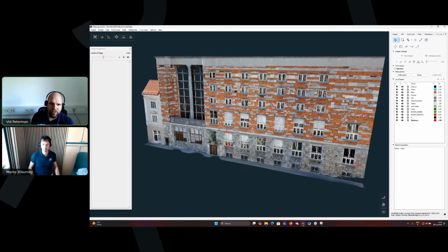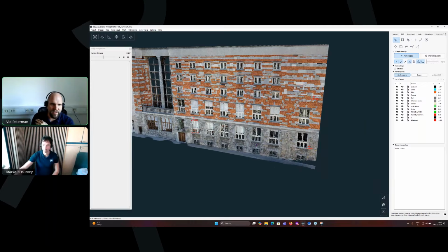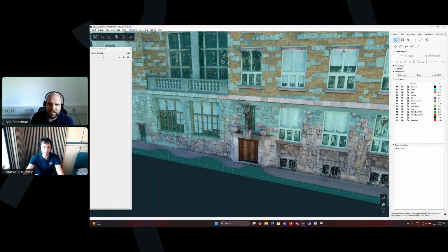So how I can go about doing that with move and copy, it will be super easy. So I will start working. So first I will create a vertical plane here. So because I want my drawing to be nice, one more time, define plane, and I want to snap on points. You know this trick, if you want to snap on a point, the best way to do that is to put the mouse on the point text. That way you always snap directly on the 3D point. Right, confirm the plane.